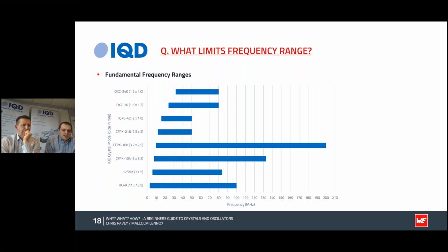Older, larger packages have enough space to accommodate larger, thicker crystals, so low frequency crystals are available, but may not be suitable if the PCB real estate is low, thus requiring a smaller crystal.